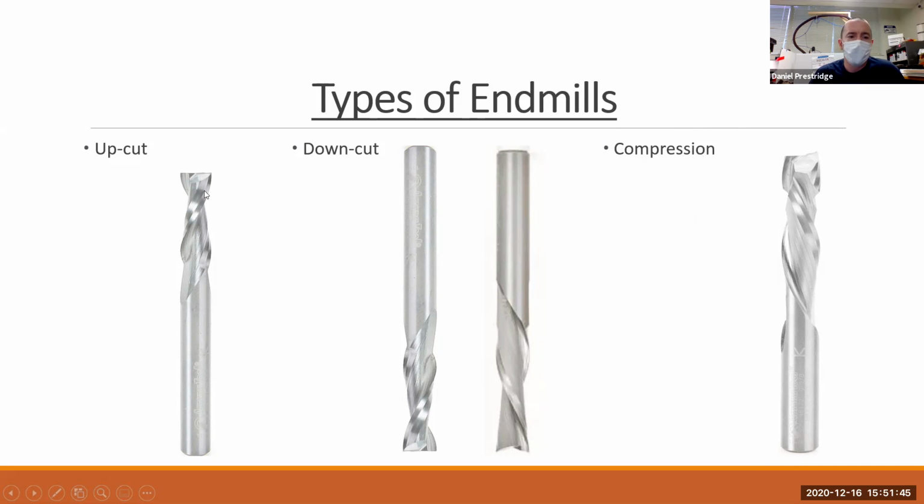That's different from, for instance, an upcut on aluminum, where we'd be looking at anywhere between 30 to 60 thousandths of an inch at 36 to 40 inches per minute at around the same RPM, like 19,000-ish RPM. So you're talking many, many multiples of what you would be cutting in the same sort of fashion, but it's the different materials and how they react when you go through.